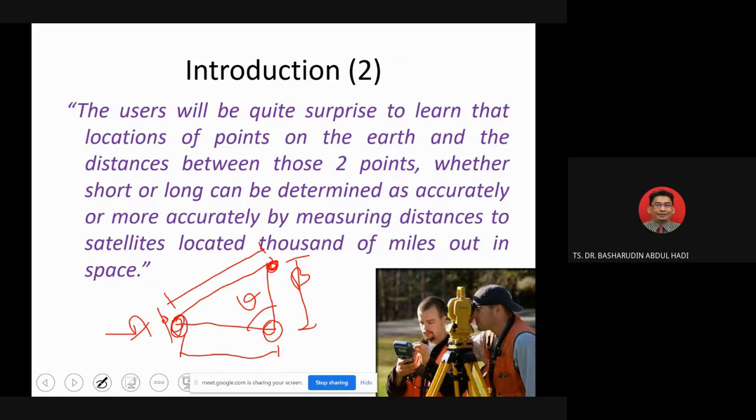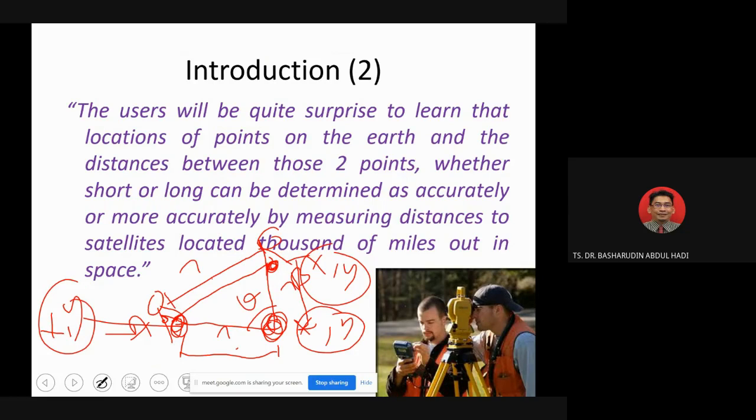You put GPS 1 on point A, and then you put the rover here. So automatically you know the distance. And then you put the static here, and you know this distance, because they give you X, Y coordinates, like on a paper graph. So from these 3 points, you know the distance and you know the angle, because they're using the coordinate system.